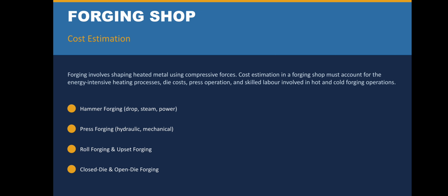So the fifth one is punching. Punching is the process of producing holes in a workpiece. It is done by placing the workpiece over the hole in the anvil or a cylindrical die of the required size, or over a hole of correct size in a swage block.